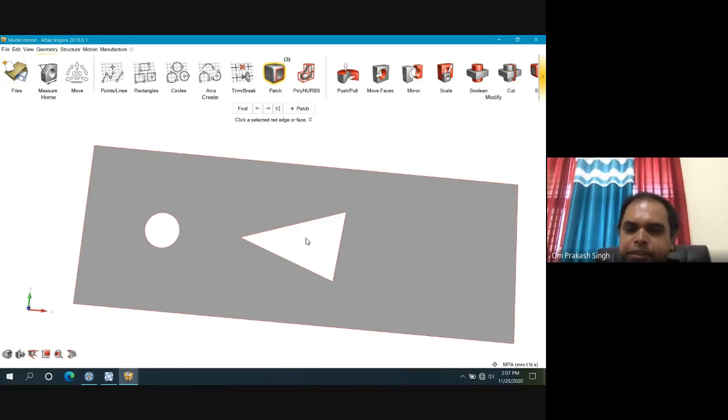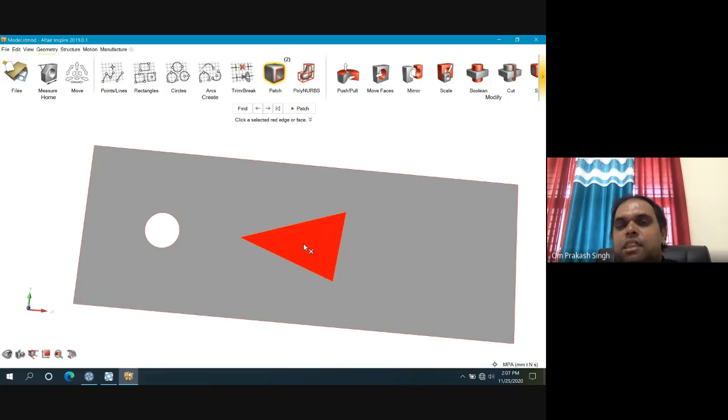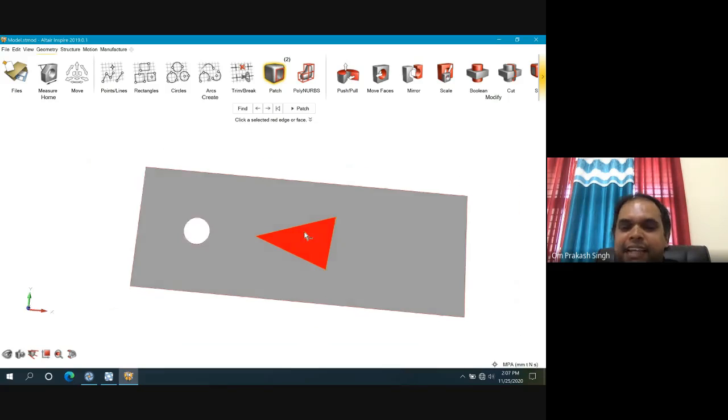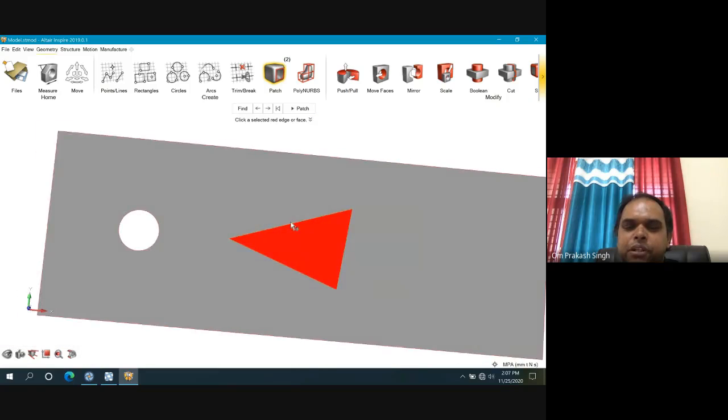if it is a solid object, you want to see the temperature of this solid blade or whatever. Then in that case, you need to keep it, and then you have to assign an interface condition. So if the outside is, let's say, fluid and inside is, let's say, solid, and you want to see the temperature, this one is a solid also. So then there has to be a small interface region where you need to define the interface.